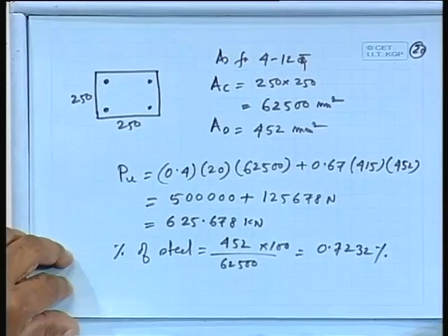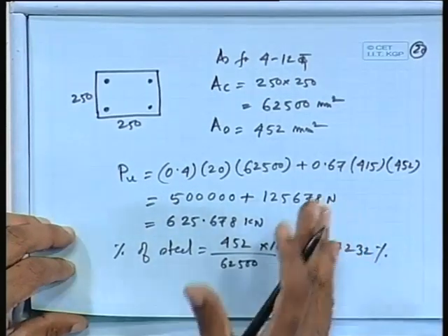And here generally we check those things. In design of reinforced concrete, the bending moment, shear force or axially loaded column, axial forces, all those things you will find out it is very less. But even then you have to provide certain minimum from the point of view of crack, shrinkage, creep, and lot of other things also involved, stability. So, from their point of view you have to provide that minimum reinforcement or minimum dimension, and for that you have to follow IS 456.